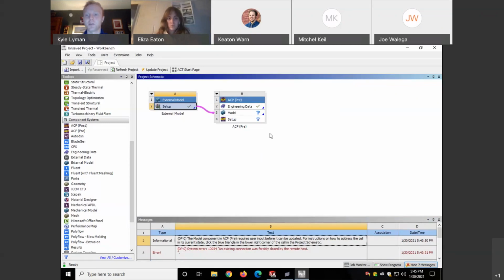So you're saying the triangles will act as if they're artificially stiff at the ends, way stiffer than the material properties allow them to be, just at the vertices. Right, because that element was designed to do a stress profile across a quad element. Now you've taken one edge and collapsed it to a triangle, and in that area, it's going to be stiff. Okay, that's good to know. Yeah, I did not know that, but thank you for looking that up. So yeah, check your element type before you export it.